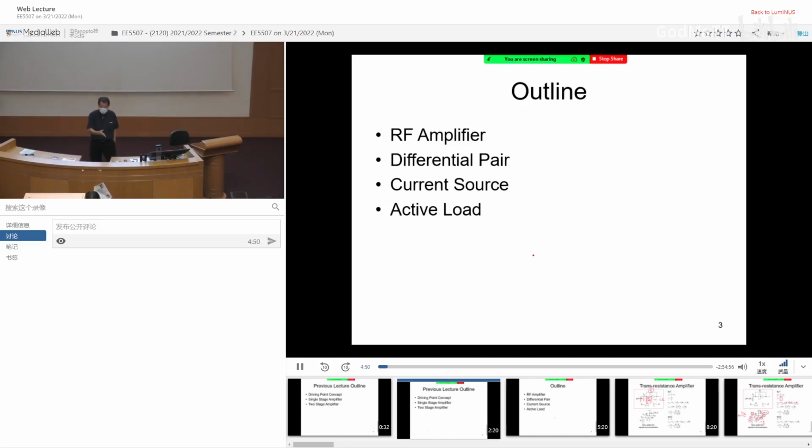For MOSFET it is the square root of 2 kn ID, drain current. I can give another example. ro for BJT is the Early voltage VA divided by IC. For MOSFET it is 1 over lambda ID. So all the small signal parameters depend on current. If you use a current source to bias a circuit, your job is almost half done, because once you know the current, you know everything.